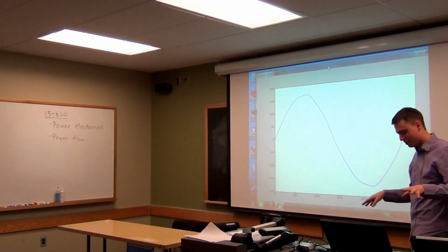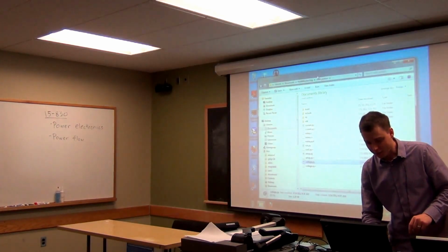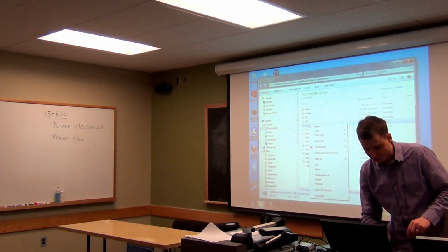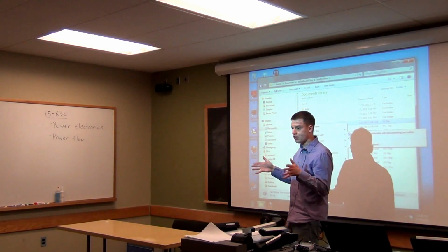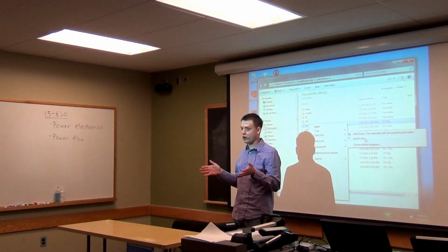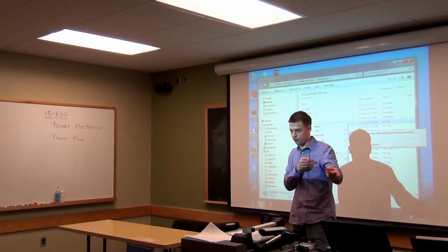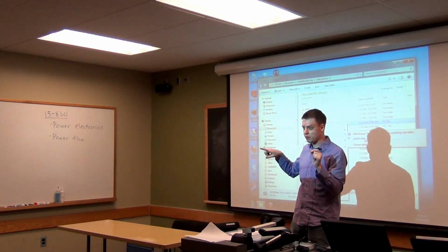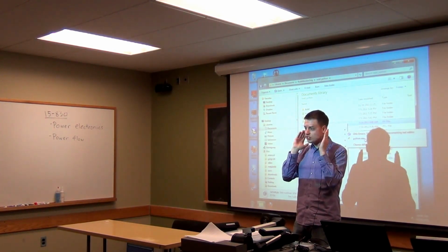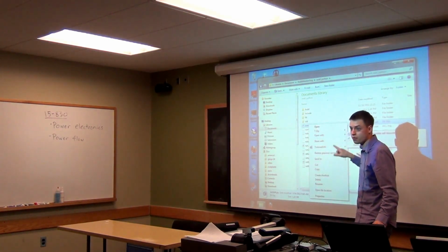Remember, now what I've done is I've plugged this current transformer onto a wire. And what I'm going to do now with what this picture here actually shows is the following. I'm going to take these current waveforms and synchronize them to the voltage. As you'll see in a second, it isn't always easy to find that sine wave for current signals. But what you can do is look at these at the same time and just draw the corresponding current waveforms for that sine wave of voltage you saw before. So that's what I'm going to draw now.